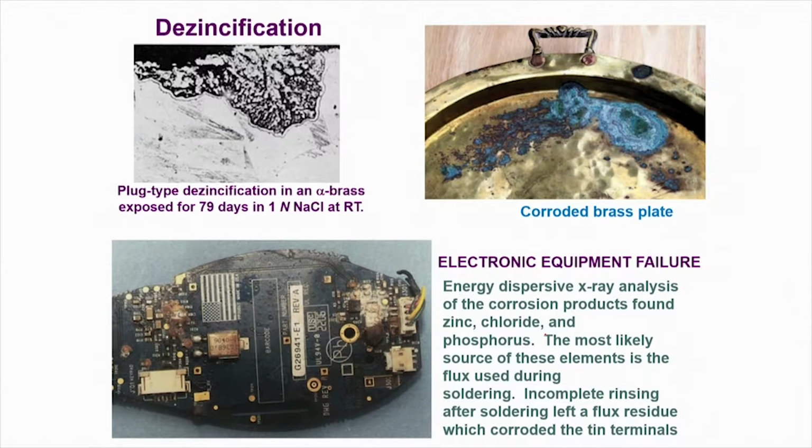Materials can degrade over a period of time because of various other possibilities. Even before corrosion starts, because of interaction with the environment, there could be gradual loss of alloying elements. So for example, when we talk of brass, we are talking about copper alloyed with zinc, and this zinc is the element which provides the strength and various other important properties. Now if you expose this in a chloride containing atmosphere, gradually the zinc can be leached out by the action of these chlorides, maybe HCl, or simply the chlorine in water can preferentially attack zinc and then dissolve zinc.